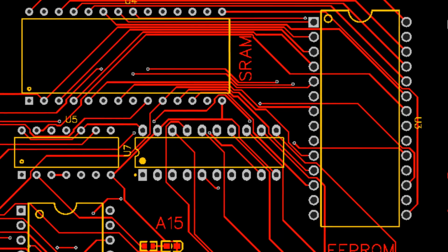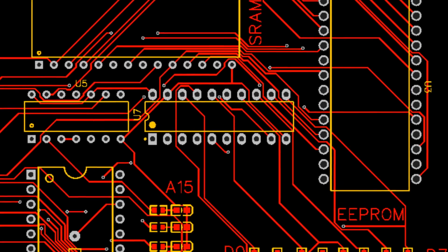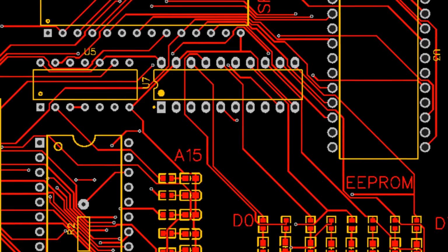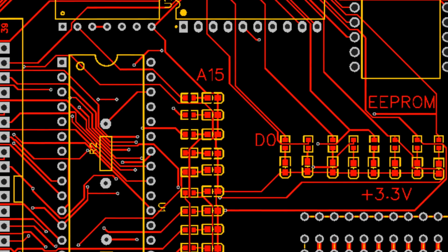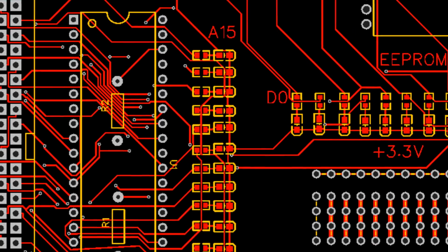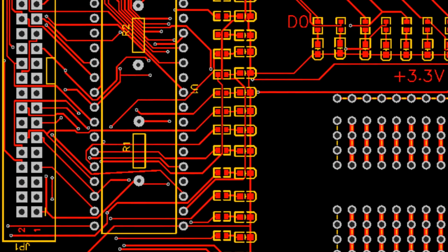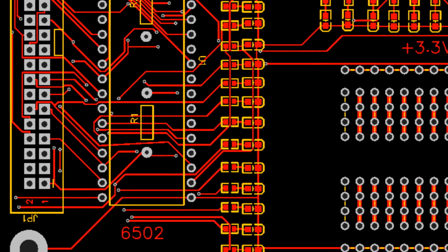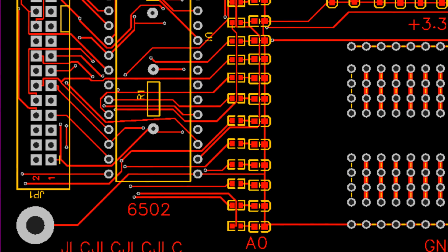Another big problem is the lack of power decoupling for lower frequencies. While running at a lower clock speed, when the address and data LEDs turn on and off, they cause big spikes in the voltage that the FPGA board supplies. If I would have added some capacitors close to the LEDs, that could smooth out their power usage.